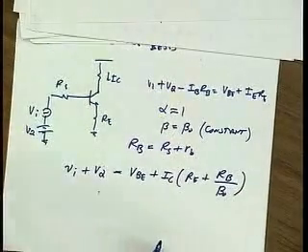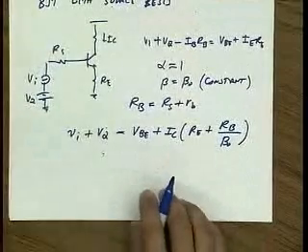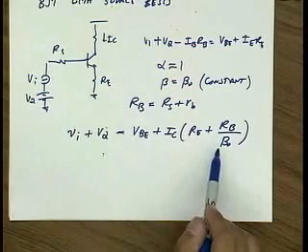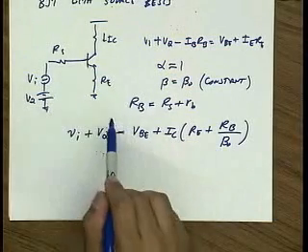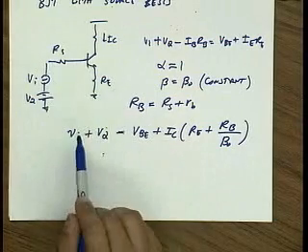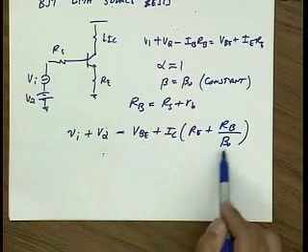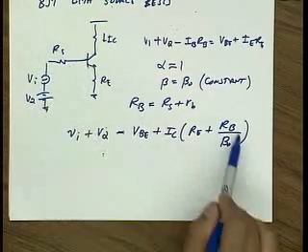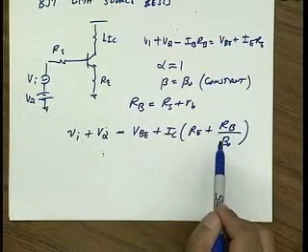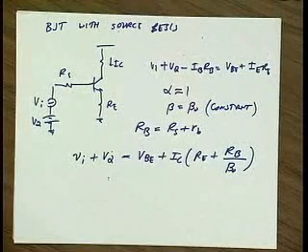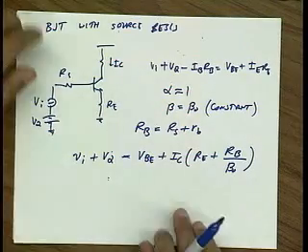In other words, as you guys know from your basic electronics courses, I can take a resistance and move it over to the emitter by just scaling it by beta, because the emitter current and the base current are always related by beta. So in other words, I can absorb any kind of source resistance and treat it as a feedback resistance in the emitter. Okay? Questions? All right, well, what about an emitter follower?